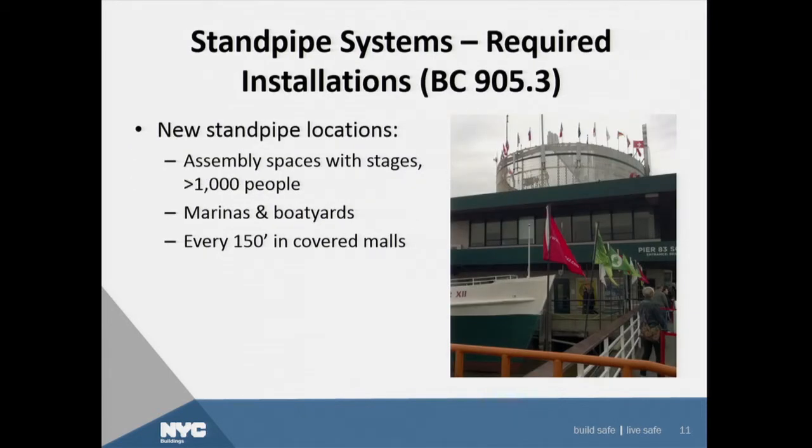New standpipe locations. If you happen to be designing an assembly space with a stage and greater than 1,000 people, you must have a standpipe location that didn't exist before. For a marina or a boatyard, there are certain provisions that are in the fire code, but we send you there, and in certain covered malls.